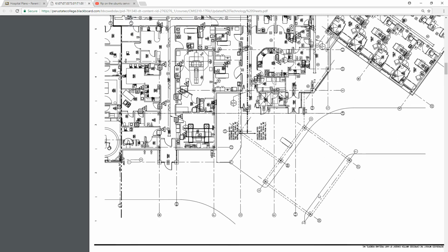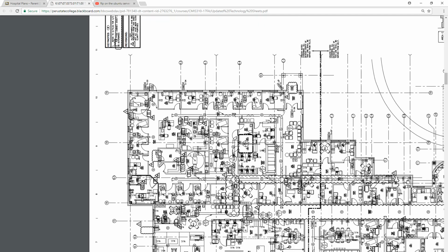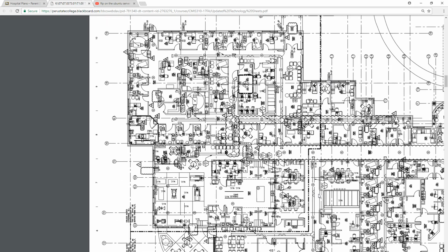So this hospital is already currently being redesigned and added to. It's a fairly large facility for a small town. This one was about 65,000 square feet. A couple of other things you'll notice in this drawing, these things going through the hallway right here. And I know if you're online you're not going to see that, but in the middle of these hallways there are lines with little W's in them every once in a while. Those are ladder racking. That means in the center of that hallway, up above the ceiling tiles, is a grate that we can put cables on everywhere we go.